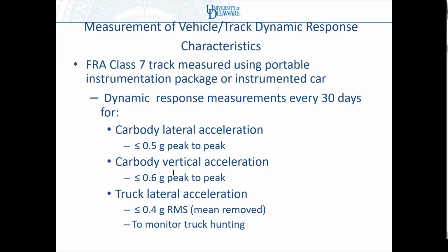So track-train dynamic responses are becoming more and more critical in defining how we look at the excitation of the track to the vehicle. And so the newest generation of standards for track geometry have started to include dynamic response characteristics.